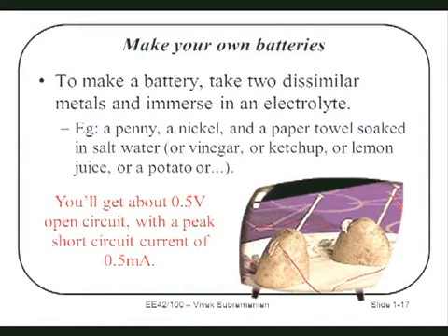Okay? What you do is you take a potato and you stick 2 pins with dissimilar metals into it, and the potato is moist and has some electrolytes in it, and it turns out you'll be able to measure a voltage and get decent current out of it. So you can make a potato battery, and this 0.5 volts, by the way, is enough. If you put 3 potatoes in series, it's actually enough to run an LED. Okay, and you can actually do it.